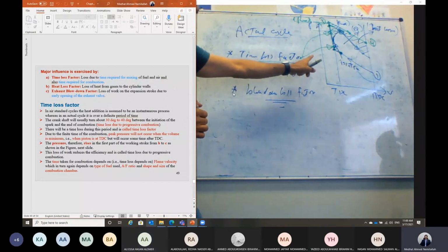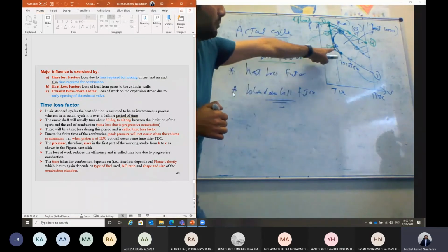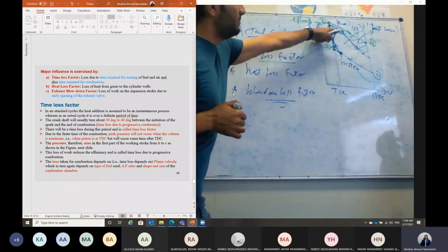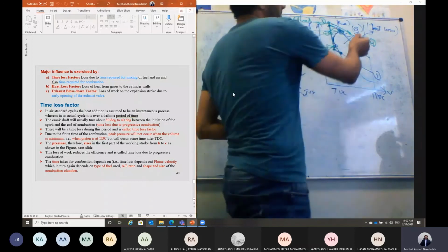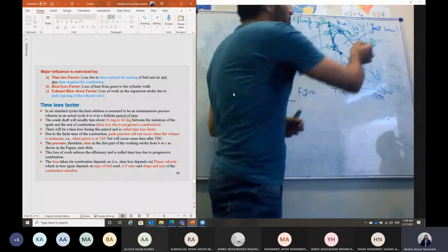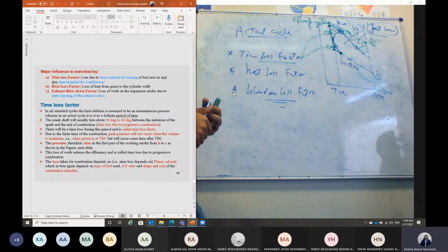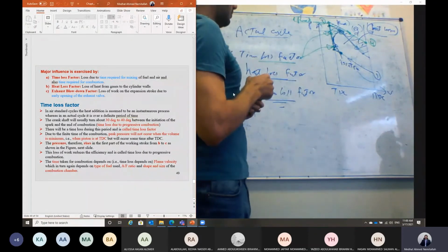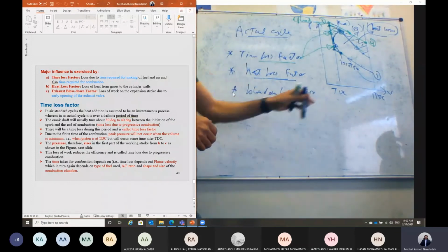Yes. So we should have the time loss factor due to the progressive combustion, which needs time to take place, and it can be represented on the PV diagram by those two areas. And then we have net work losses due to the heat losses to the cooling water and the lubricating oil in this case. And this, guys, can be related to what we call the heat loss factor in this case. But what about the blow down loss factor?